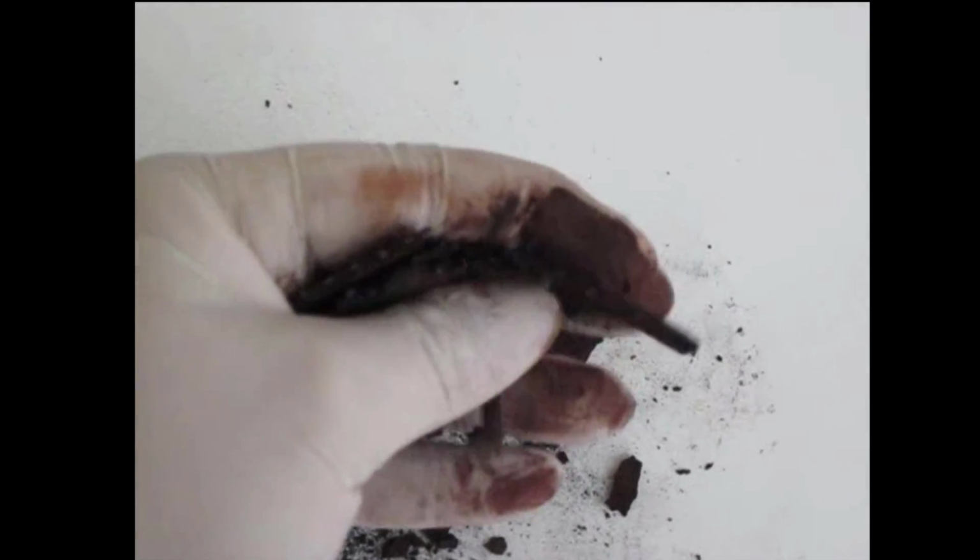It's very, very delicate. The reason I wanted you to see this video is to show you just how delicate these plates are and to really express to you that a battery needs to be secured with its hold down bracket, holding it in place during travel. In the course of your career, you may encounter vehicles that don't have adequate hold down. You need to make sure that that gets fixed or that battery will fail prematurely.